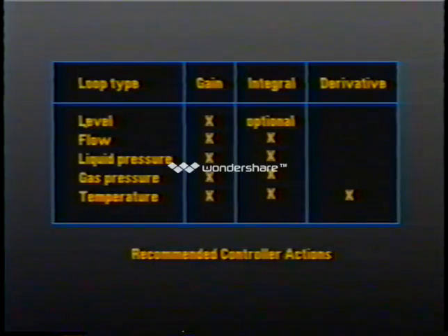Proportional-only control is generally used to control liquid level or other non-self-regulating processes, since the process itself acts as an integrator by generating a continuing change in error. This will normally bring the process variable back to set point by causing continuous repeats of proportional action.